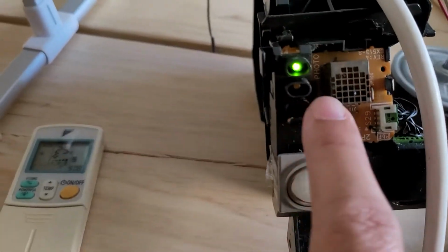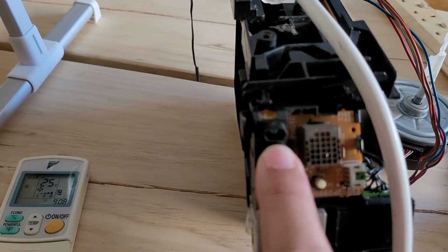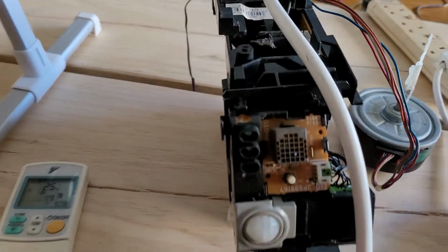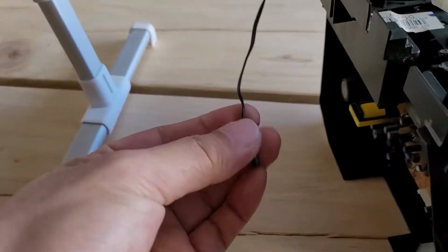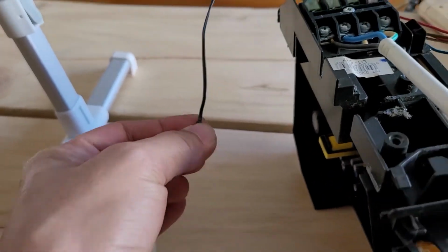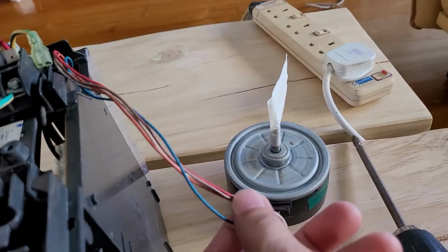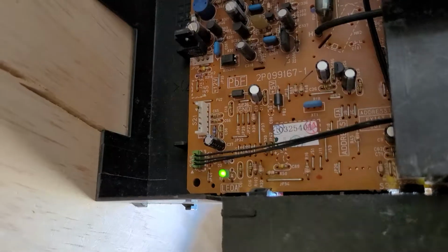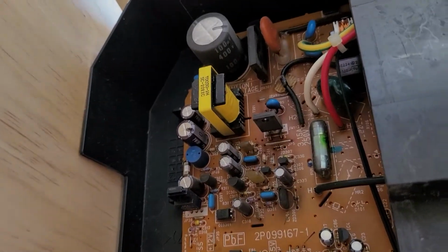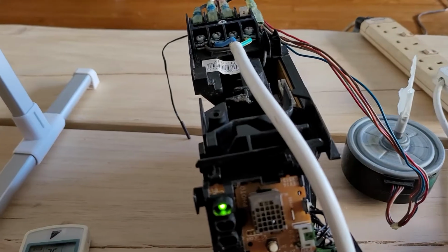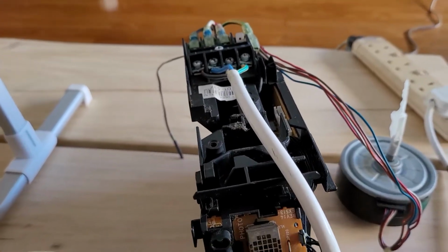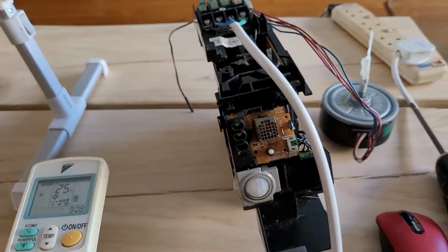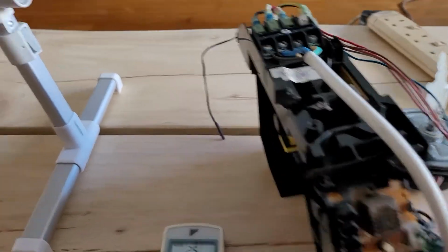For purpose of demonstration, you see if your aircon refuses to work and the light starts to blink like this, it can be something as simple as a faulty temperature sensor. We call it thermistor, faulty fan motor, faulty printed circuit board, which in short is called PCB, and a lot of other stuff including compressor failure, things like that. So it's quite smart, it can self-diagnose. So I'm going to teach you how to retrieve the malfunction code here.